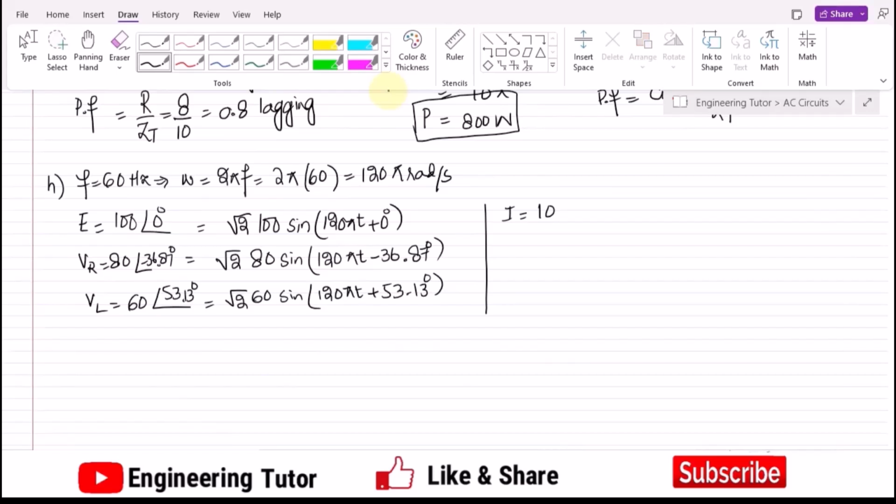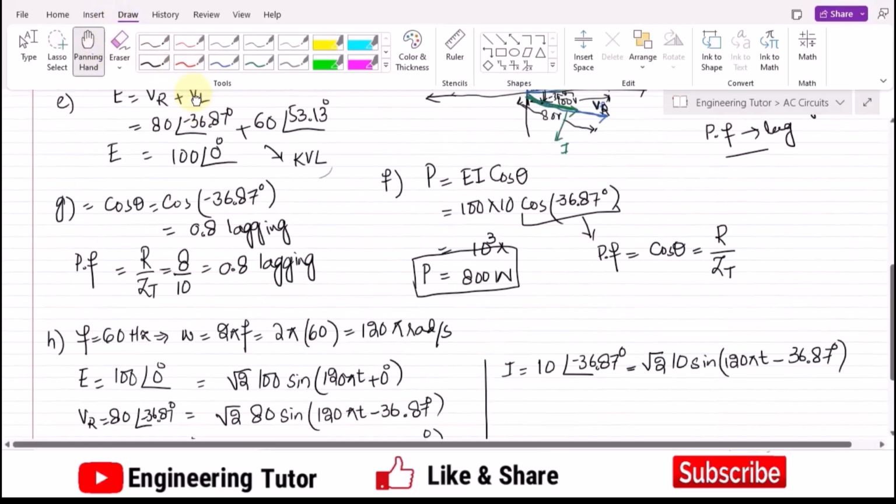10 amperes and minus 36.87 degrees. Okay, now the same rule which we have seen here, that is square root of 2 multiplied by 10, and that is sine of 120 pi t, and the phase angle it has is 36.87 degrees. Okay, so that is for the current. Here we have seen the current in the phasor form, and here the sinusoidal form as well. Okay, so what is the last part?